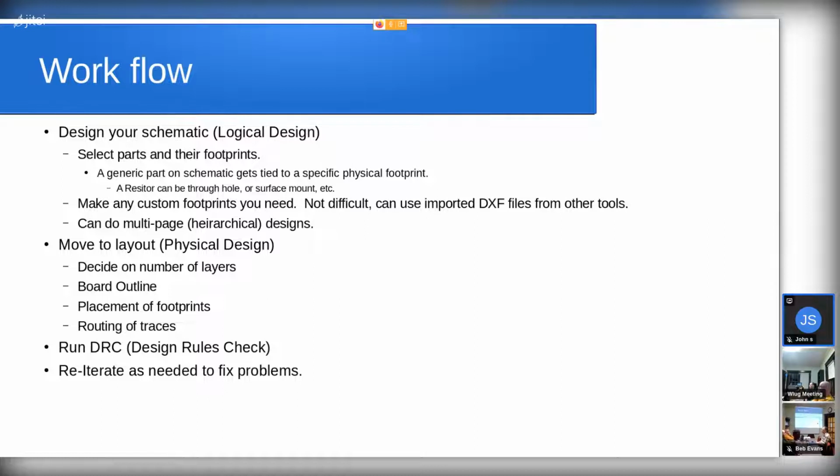I don't know the details. That's an entire separate talk on how to lay it out. KiCAD does have support for doing parallel tracks, which are matched in impedance and matched in length, which is very important when you're doing radio frequency or networking. You need to have your A and B pins for your Ethernet run so they're within a certain constraint of length. I don't know anything about laying out that kind of stuff.